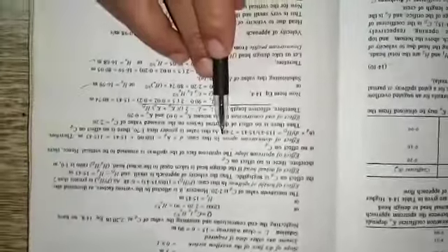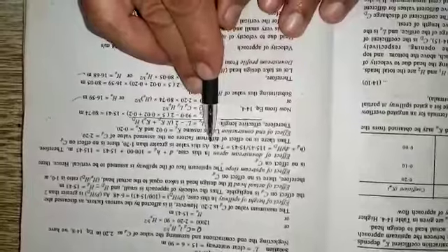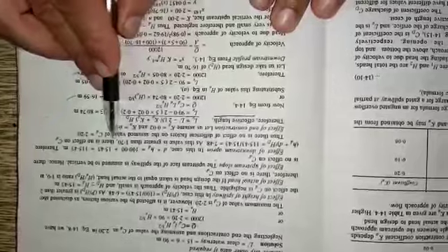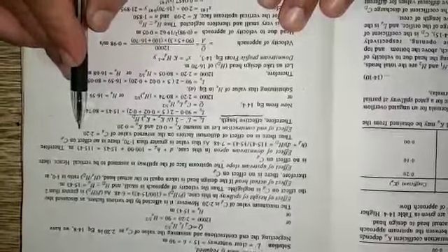Now the effect of downstream apron in this case, that is D plus HD, which is equal to 100 plus 15.43, that is 115.43 meters. Therefore, HD plus D upon HD comes out to be 7.48. As this value is greater than 1.7, there is no effect on CD. Therefore, let us assume CD is equal to 2.2.